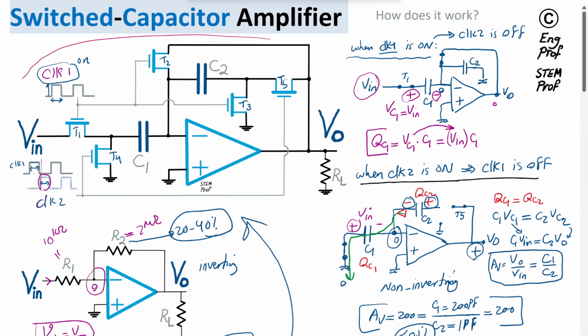This one has its own nuances, as I said before. For example, we need to be careful about how to model the switches, and how to design the circuit in such a way that the non-zero resistive effect of the on switch can be neglected, and also the open switch resistor value can be assumed to be practically infinite.